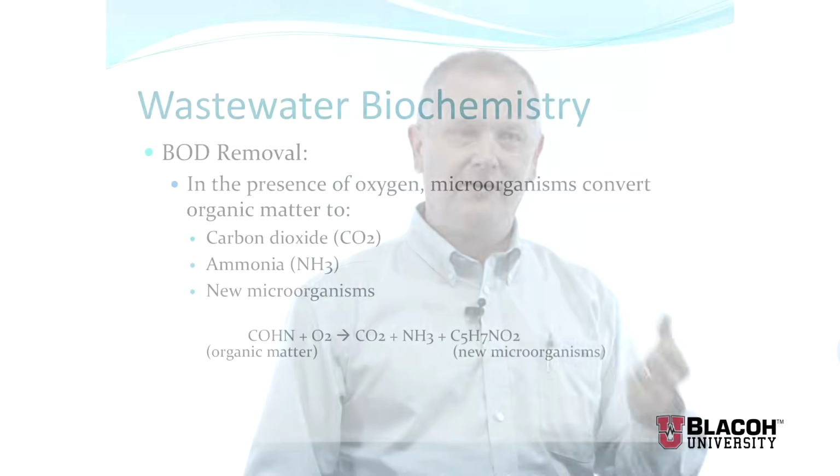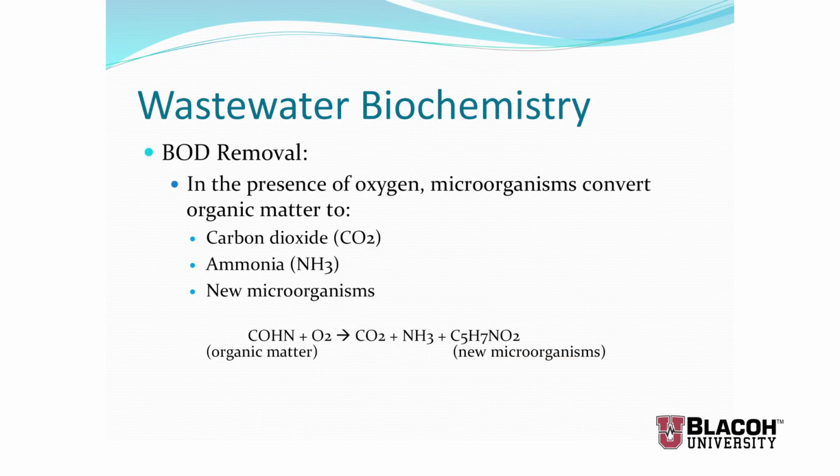Now, I said this was the biochemical equation for removing BOD. Where's the BOD in this equation? Well, remember, BOD stands for biochemical oxygen demand, meaning it's the oxygen that's absorbed in the biodegradation of this organic matter. So in a sense, it represents the organic matter. It's a surrogate for actually trying to measure all of these different organic chemicals and their concentrations. You could also say, well, it is the oxygen that's being consumed by that.